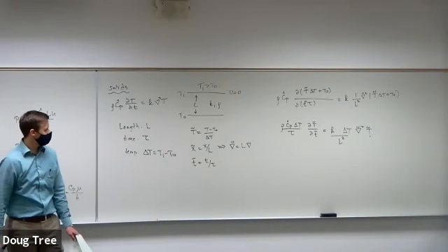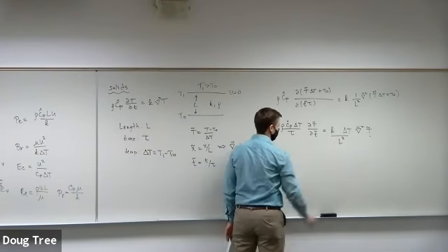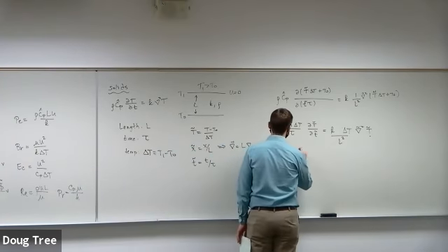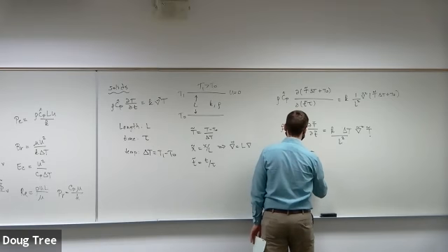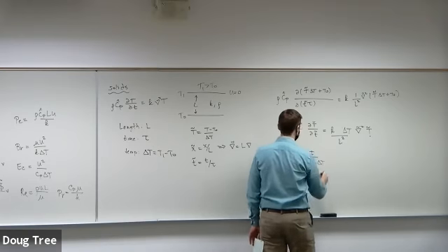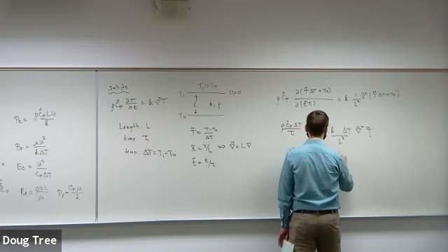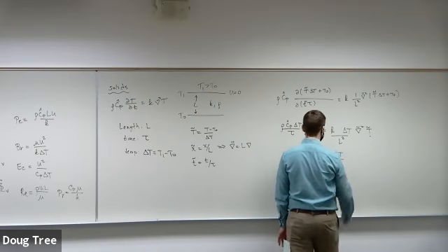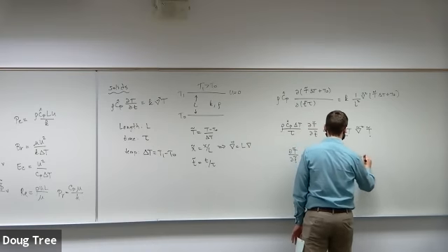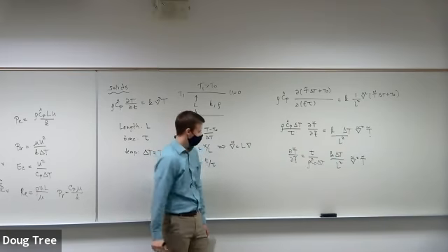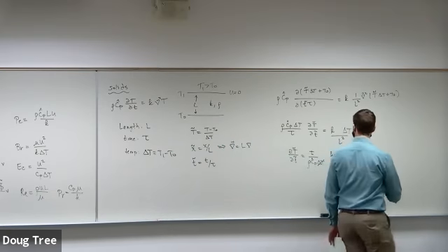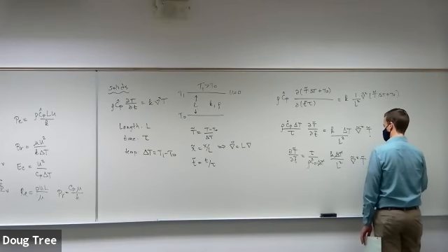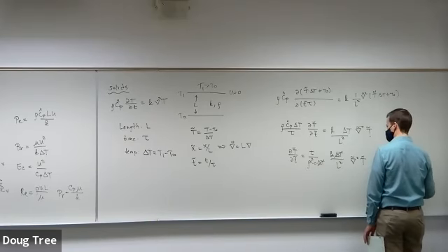Okay. So now I just need to multiply by the inverse of that term and collect. Right? So I have d t tilde, d t tilde. And now I'm going to have tau divided by rho c sub p hat delta t multiplied by k delta t over L squared, grad squared t. Okay, so the delta t cancels. I get this one term, which is tau divided by L squared, k divided by rho c sub p.